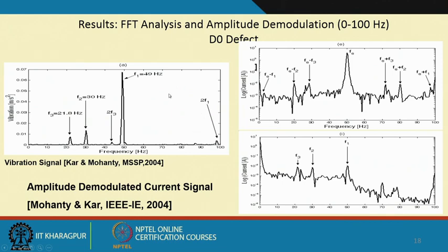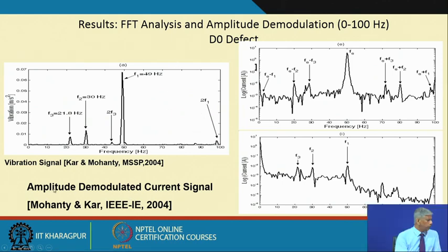But this is the case wherein we see FFT analysis and amplitude demodulation from 0 to 100 hertz. So, this is the vibration signal obtained from this gearbox, wherein I can see all the input frequencies, and that is what is expected.